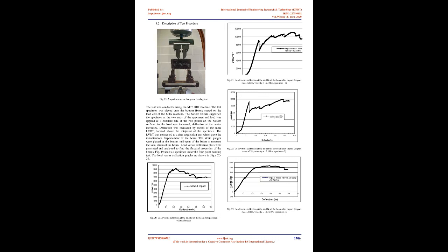To the contrary, the damage by a lower weight hammer is localized and the effect on the load carrying capacity is also limited. Because of this, it is expected the effect of the impact on the residual load carrying capacity will be different depending on the hammer weight. This will be examined in the next section. 4. Residual bending strength using 4-point bending test.